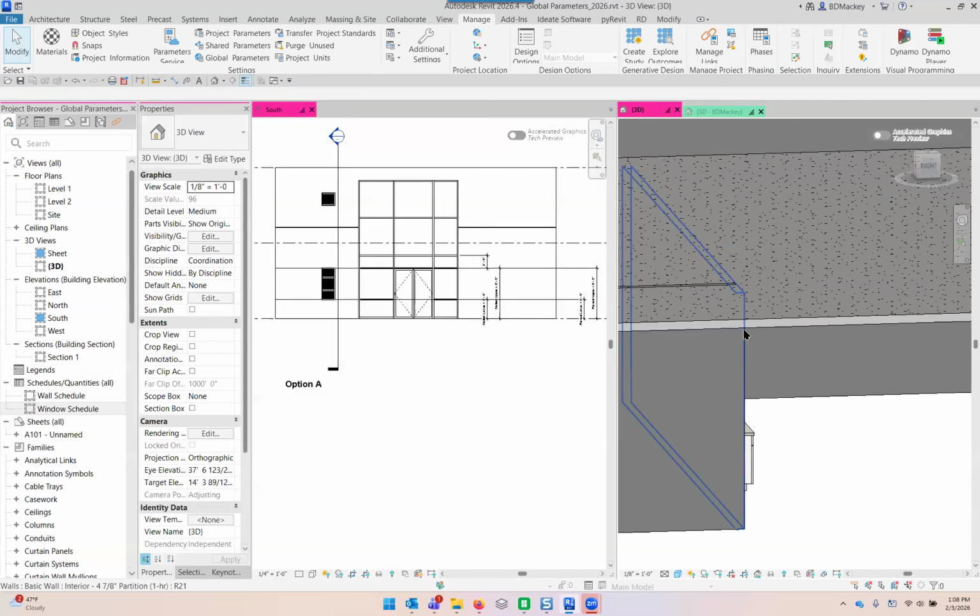That's not happening. What I've done is I've actually just toggled the top offset for this floor with a global parameter, right? So in Revit world, what you can do is have a global parameter that is a reporting parameter. So if you see I select this, it's saying, cool, I'm going to grab the floor thickness. So basically I did a dimension from a level to the underneath side of this floor. This would work if that was linked in via a structural model. So I could dimension from my own level to the underneath side of a structural model and create in Revit what is called a reporting parameter. So you're going to see I've got the reporting parameter down here called my floor thickness at level 2.